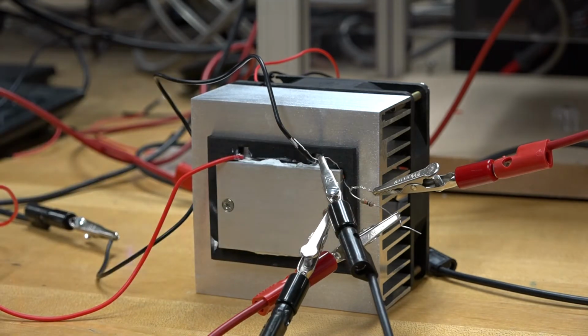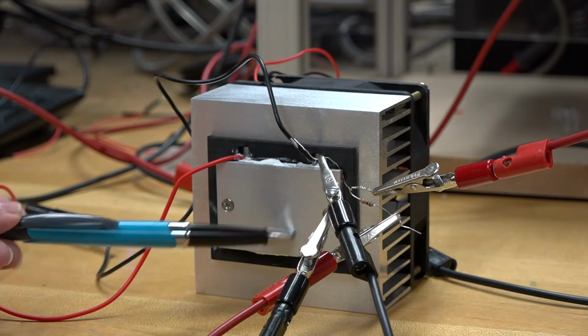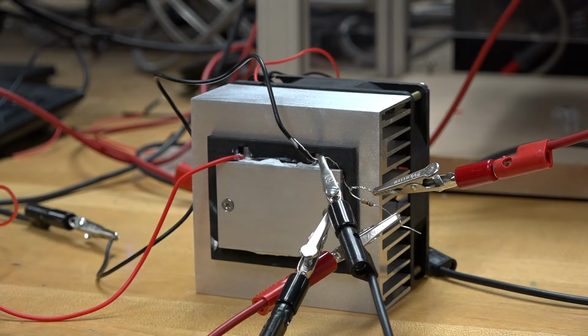We want to measure the voltage drop across the thermistor as the current of the Peltier device increases, and from that we measure the temperature of the heatsink, the cold side of the Peltier device, based on the change of current supplied by the power supply.